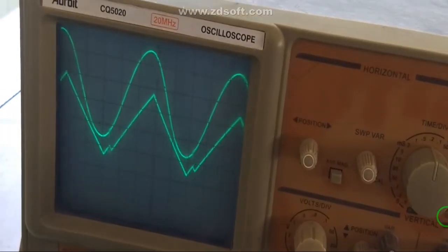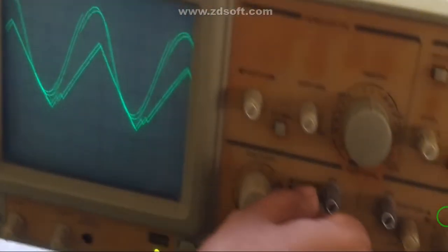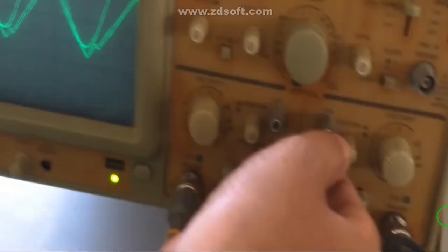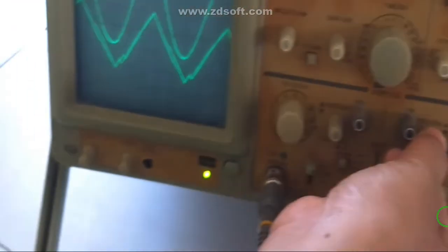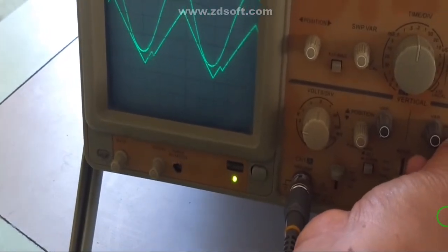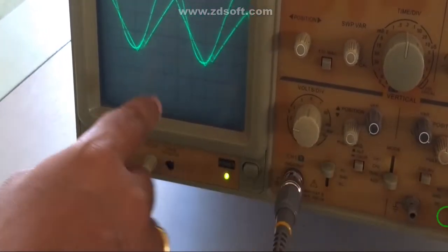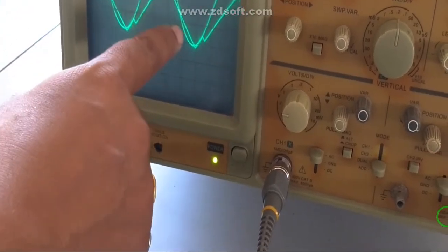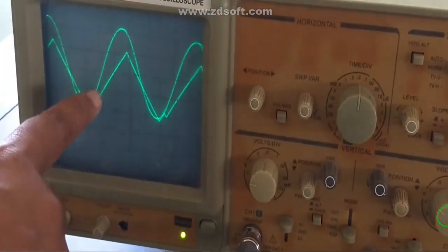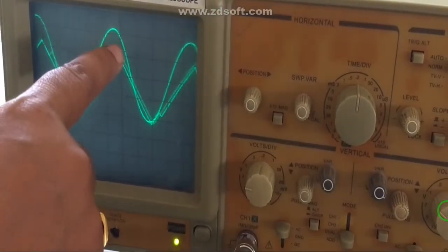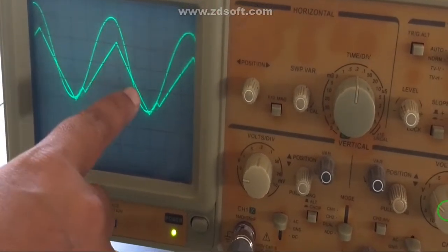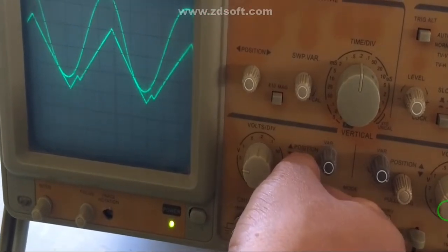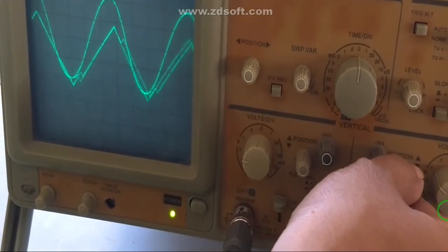You can see the channel 1 waveform, that is this sinusoidal waveform, it is your input signal, and the second channel output is the output of your integrator. So you can observe how this integrator output is going to catch your input signal. As we know in DM, the step size is constant, the rate of rising of that ramp signal is what? Constant. So you can compare the input and your integrator output.